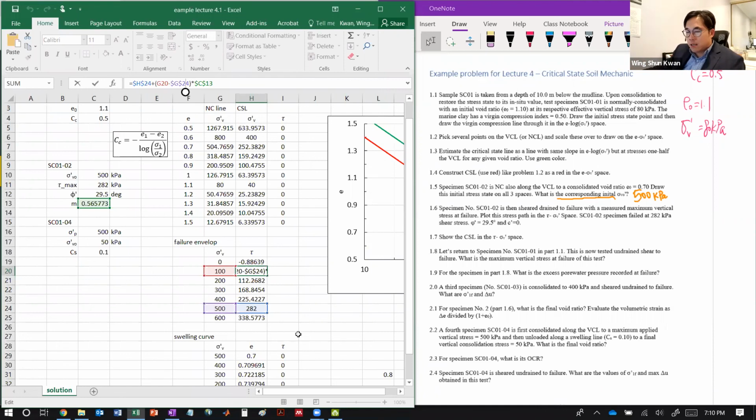So you know the points. And if you know the slope, and the slope is related to the friction angle, which is given there, then for the given stress, you know the point and you know the friction angle, so you can find out the corresponding shear stress. So that's what we have been doing right there.